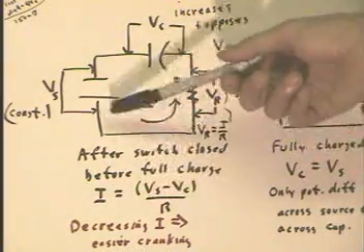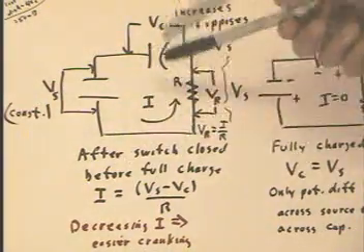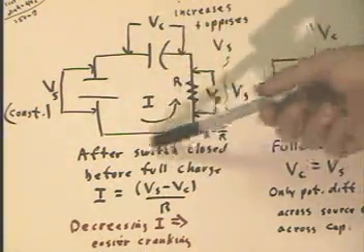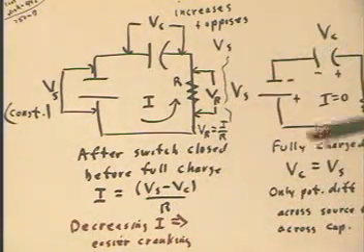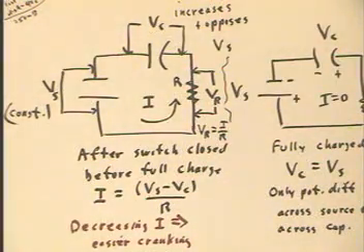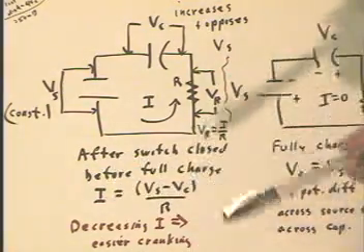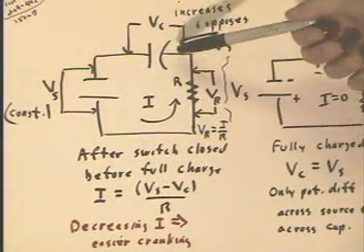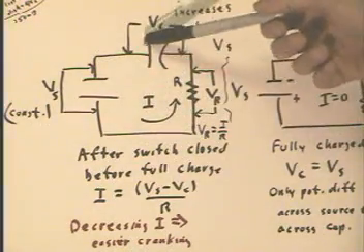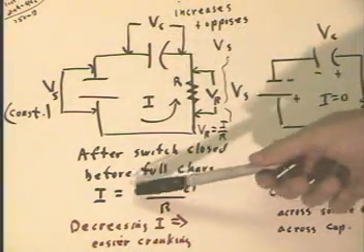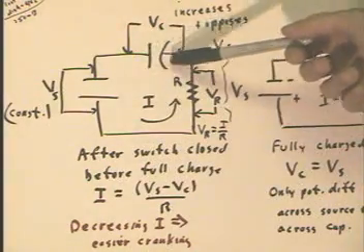And what we get then is at any instant the current is going to be the total voltage, which is going to be the source voltage, which goes this way, minus the capacitor voltage, which is pushing in this direction, divided by the resistance. That current is exactly what deposits charge or takes charge away from the different plates of the capacitor. So this current is the rate at which the charge in the capacitor changes.